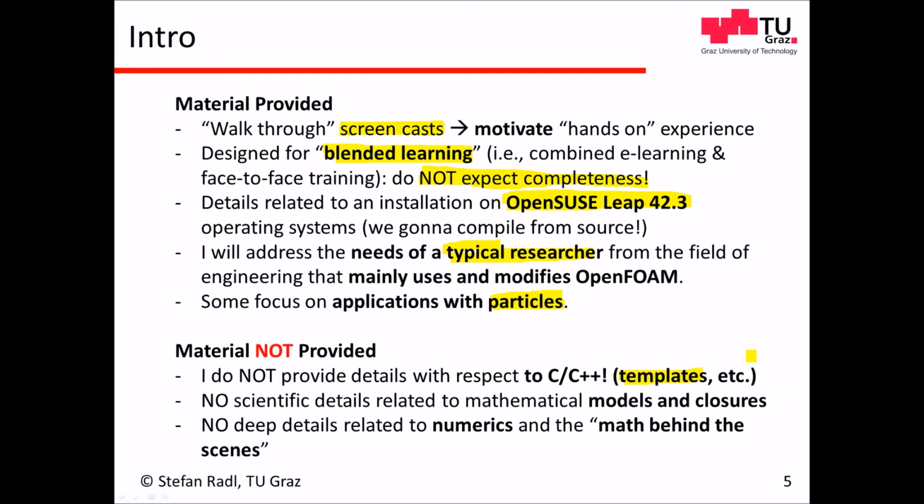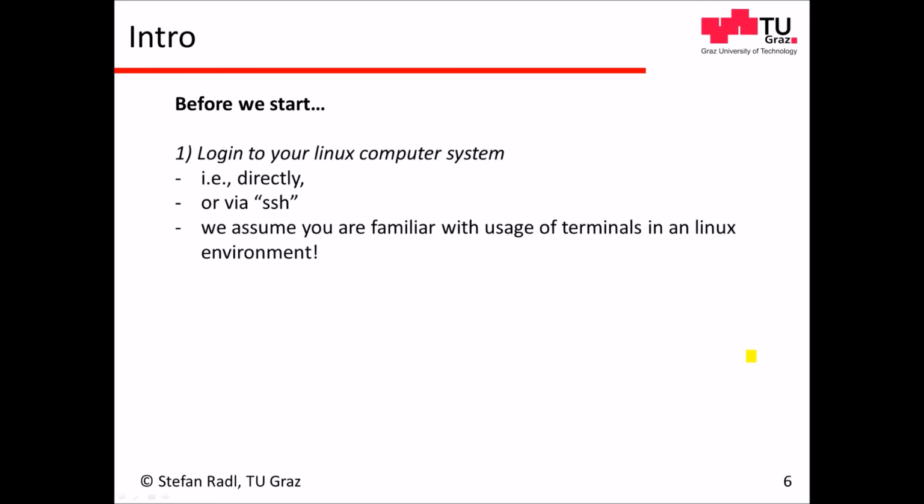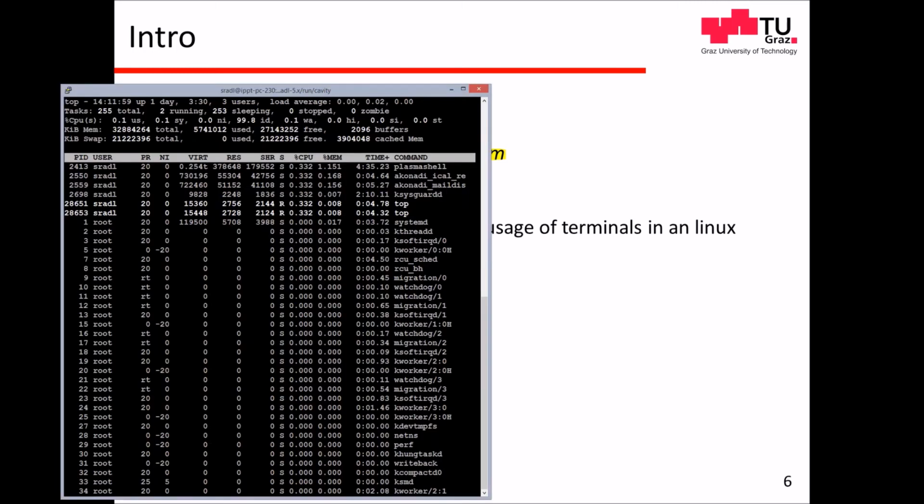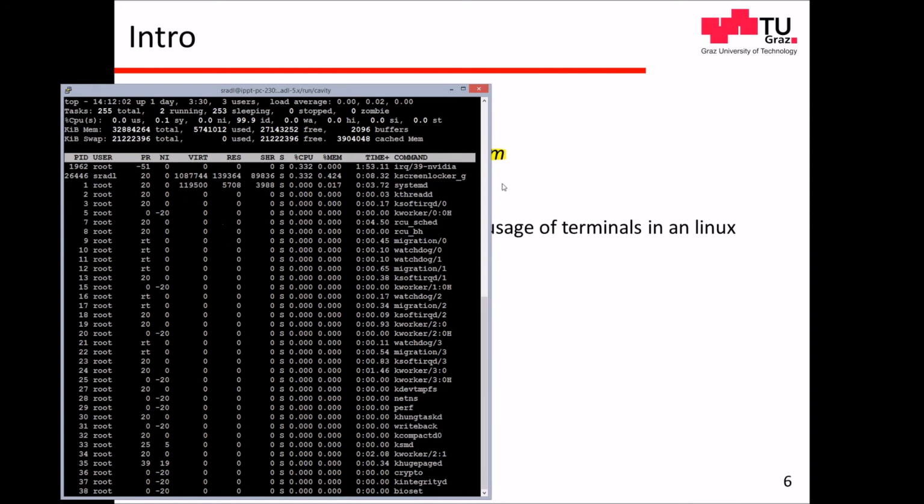So now we can come to the preparation steps that we need to take before getting involved with OpenFOAM. Certainly, first we need a computer system, and when you work with OpenFOAM, it's very favorable to have a Linux computer system. OpenFOAM is designed for Linux, and there are some ports to Windows, but it's definitely just a port, so be careful.